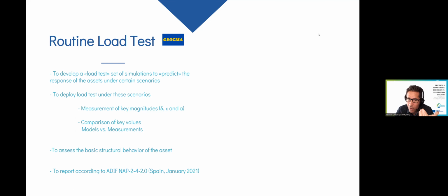Then to deploy the load tests themselves and measure key magnitudes: deflection, strains, and accelerations. Then we compare those key values between models and measurements to see how the asset is behaving, which helps assess the basic structural behavior of the asset.